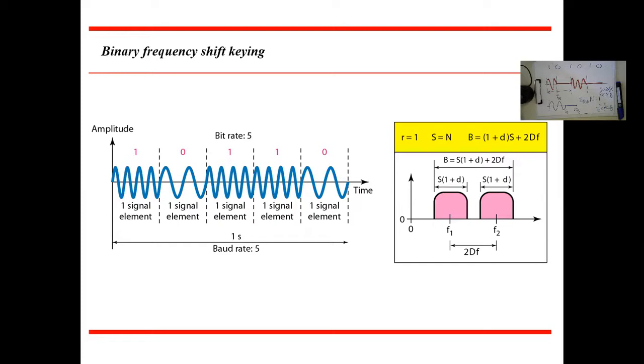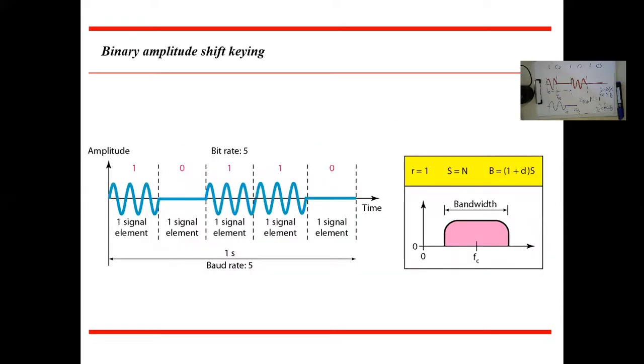But here there is one very important point to consider whenever you are considering the noise immunity of a digital modulation. In the AM analog modulation, your carrier envelope changes with respect to the message. So whenever you have an imposed noise, this noise will affect the detection capabilities to reconstruct the message. However, here we don't have this problem because you have only 2 levels of the message.